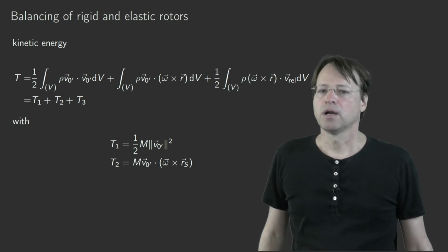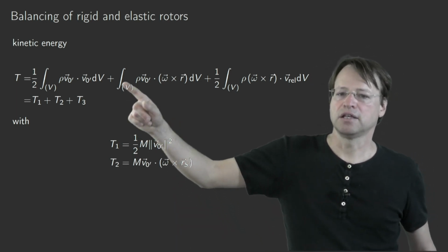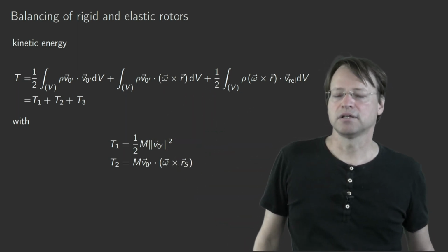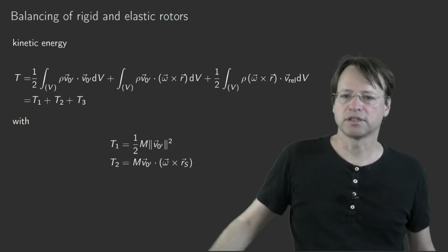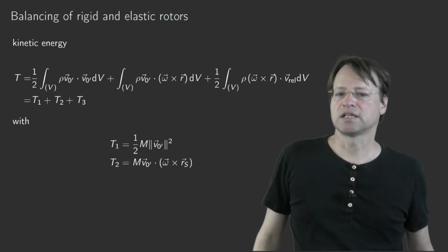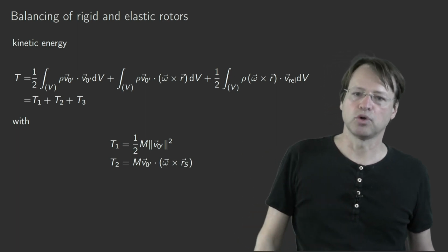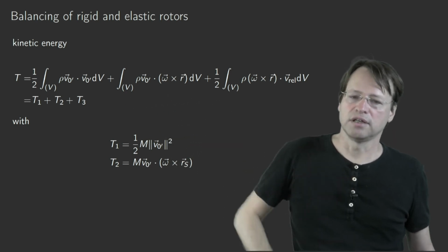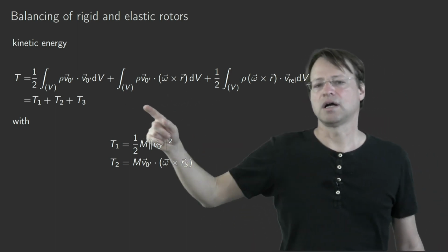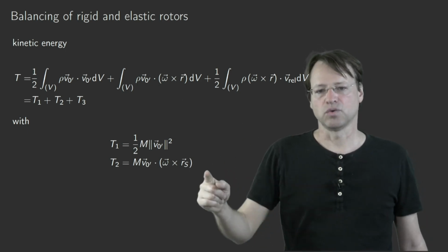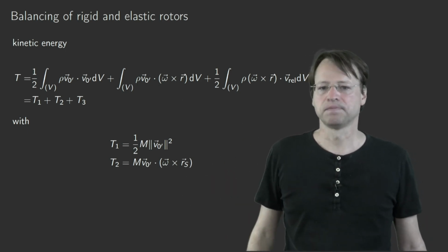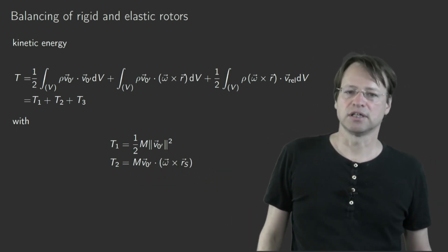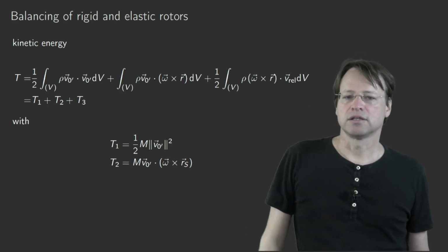For the second term, we also can simplify that equation because VO prime and also omega are independent on space, on the spatial coordinates. The only thing that depends on space is that R is the position vector starting from O. Well, you know that, then you can integrate over R dv, and you know that the result from integrating over R dv is just the information where is the position vector to the center of gravity, that should be known, and multiplied by the mass m then. A classical result that you obtained when you studied the static mass moment.